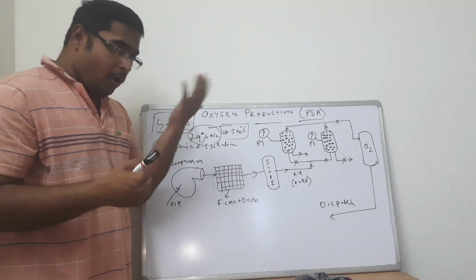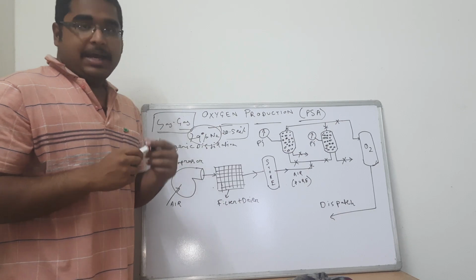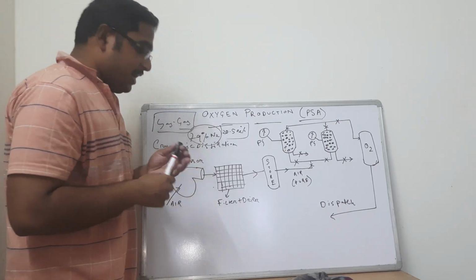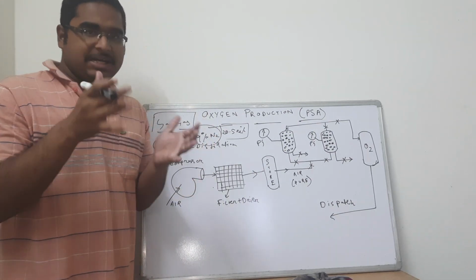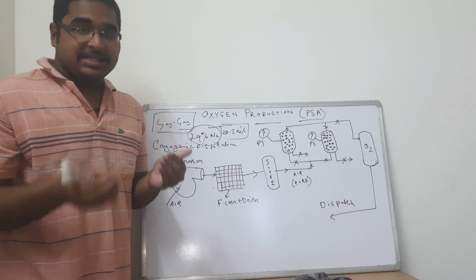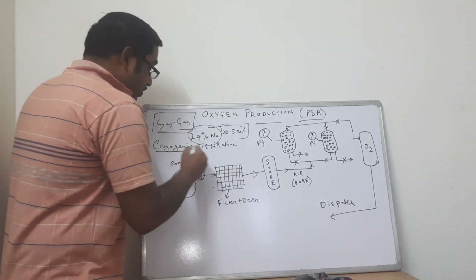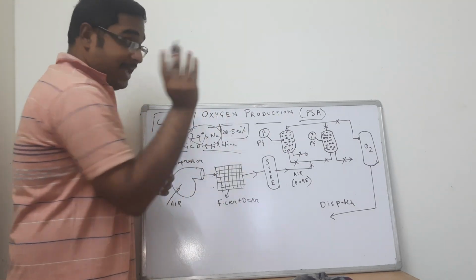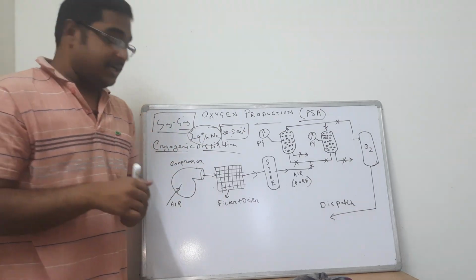having a lower boiling point than oxygen will tend to remain primarily as liquid, and the oxygen, having a tendency of easily forming vapor, easier than nitrogen, has a tendency to primarily remain as vapor in a distillation column. Using that principle, cryogenic distillation is followed to separate oxygen and nitrogen from the air in itself, which is acting as a feed. But here we are using an adsorption method and not a distillation method.